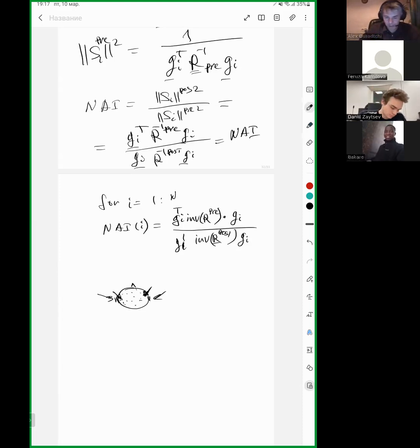But the mathematics behind them is this, and for beamformers to work properly, the covariance matrix estimate is the pivotal thing, as you understand, because nothing else they depend upon. And the accuracy of the forward model. The forward model has to be accurate enough. So for magnetoencephalography, beamformers work pretty well. For EEG, the forward model is less accurate, so they are more complicated to make work properly. But you can always do some tricks.